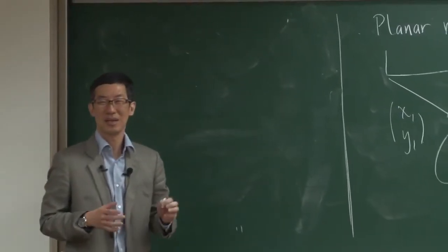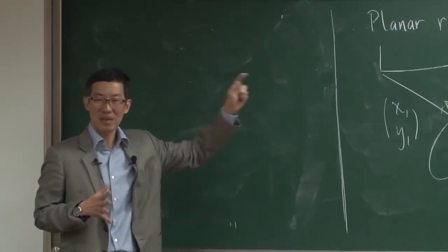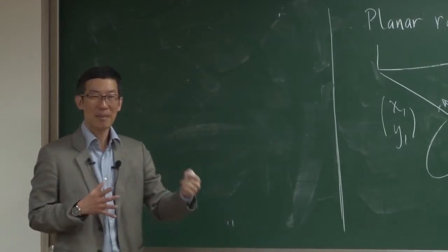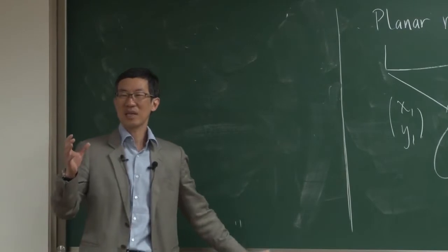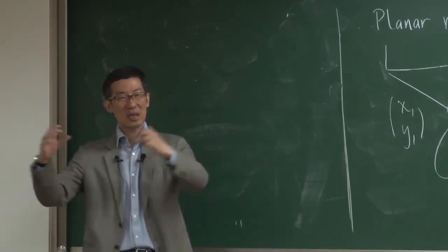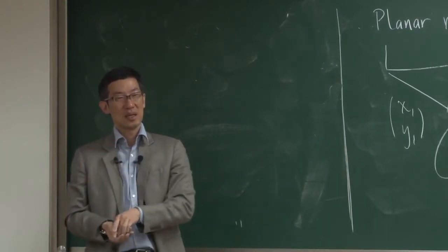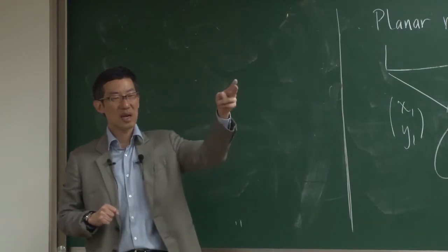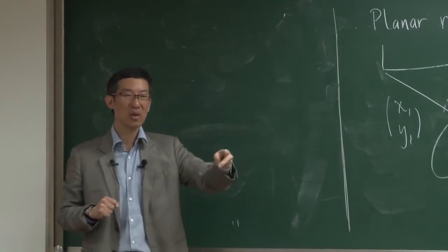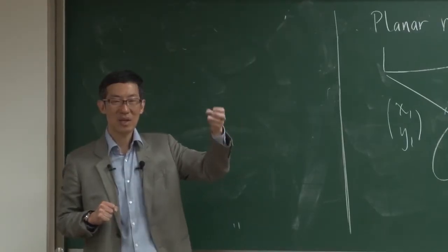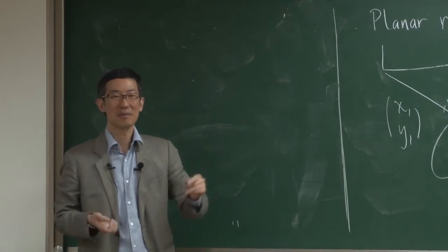Okay, so we definitely see a pattern here, right? So let's use that pattern to come up with a formula. What we've observed so far is that anytime there's a joint connecting two rigid bodies, the number of parameters goes down. If it's a 1 degree of freedom joint, it goes down by 2. If it's a 2 degree of freedom joint, it goes down by 1. If it's a 3 degree of freedom joint, what do you think? Goes down by 0, stays the same.